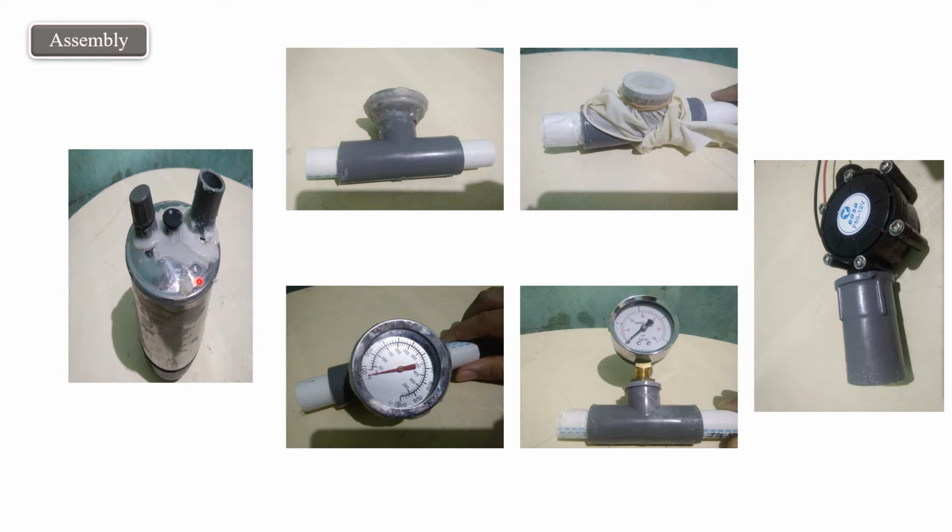The modification that we made is to make two holes in the lid. The first hole is for entering the water into the boiler and the second hole is for the steam to get out of the boiler. And the lid and the main body are stuck together using sealant glue so that the boiler that we make can be as vacuum as possible.